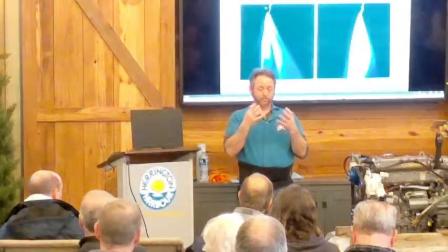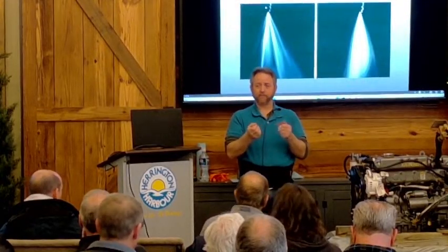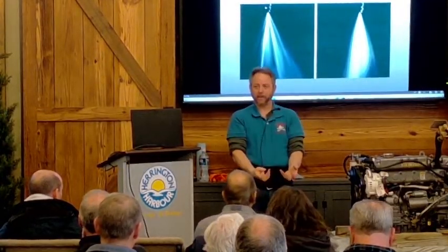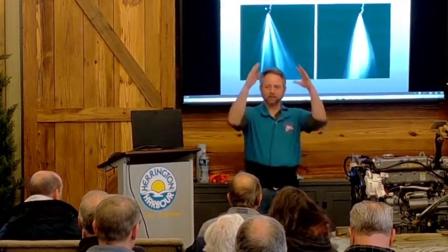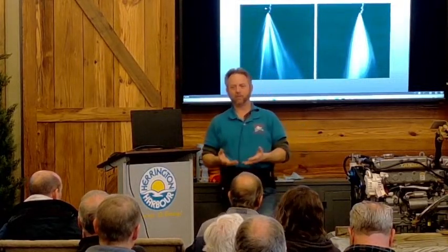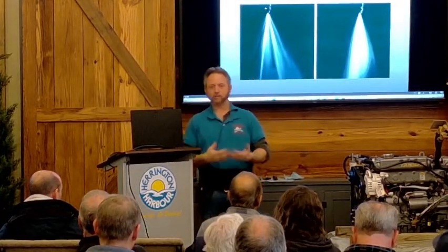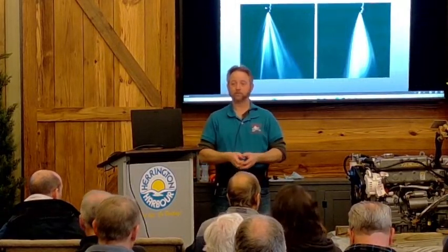And third, hot oil, once you shut the engine off, more of it will run back down to the oil pan. If it's not quite hot, then it may be a little thick and take longer to make its way back down to the bottom of the oil pan, so you won't get as good of an oil change. So the hotter you can make it, the better results you'll get.